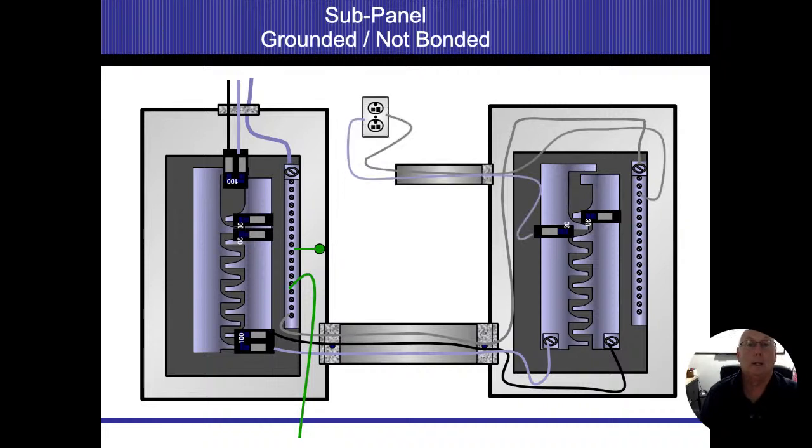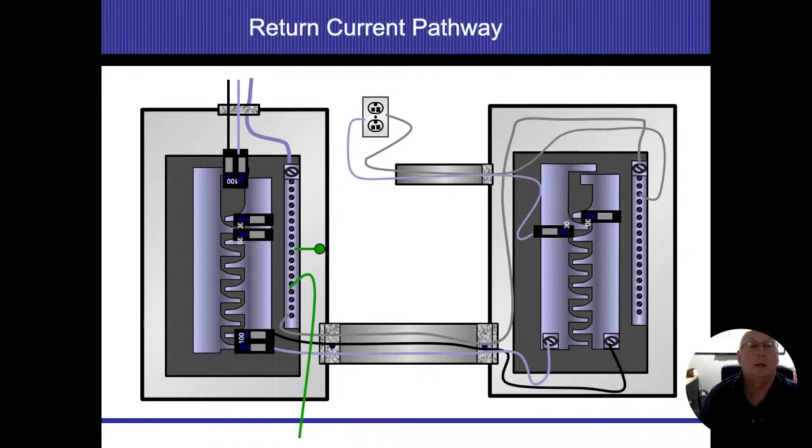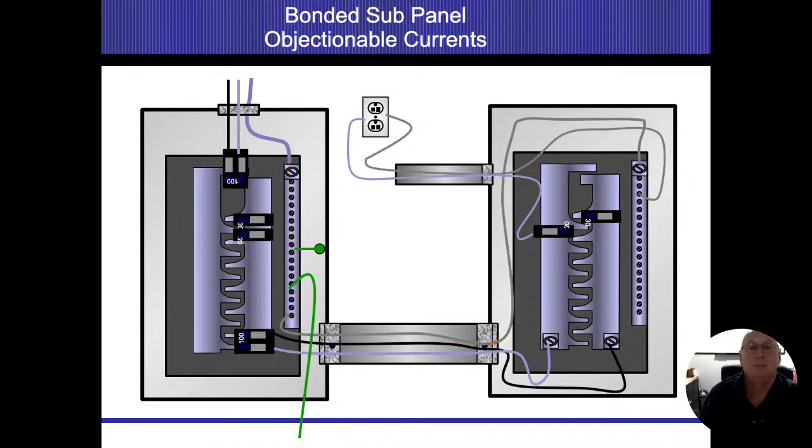Now I have a regular electric circuit. We have a hot and a neutral going to it. I'm still in a conduit system, so my conduit will be my grounding system. We're going to keep everything separate at this point in time. All right, so energy goes in through the hot, comes back on the neutral. The amperage is still flowing on the neutral. Neutral goes up and out. Normal conditions, no problem whatsoever to see here.